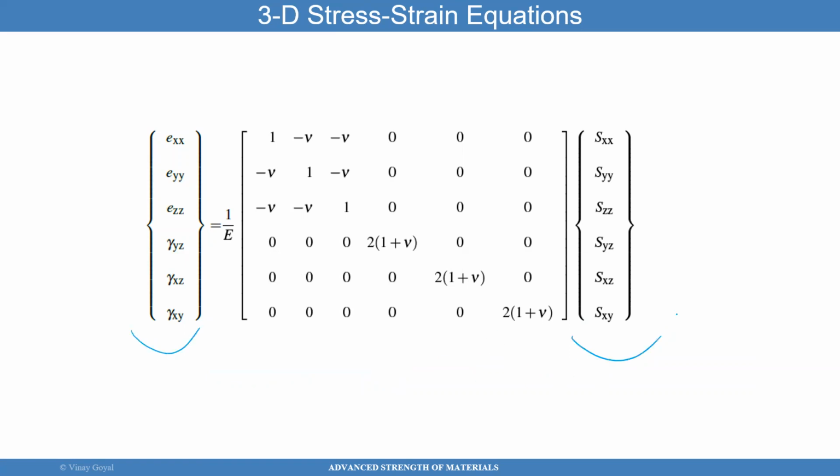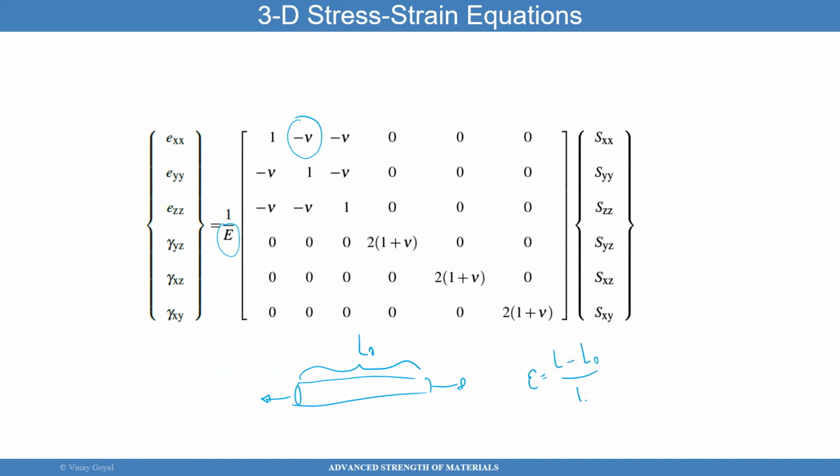And how do you calculate this relationship? You calculate that relationship using experiments. That's how you determine the Poisson ratio and the modulus. You have a round bar, right? You load it up, and then you know what the initial deflection is. So I can calculate the strain, and I can calculate the stress, and I can plot it.